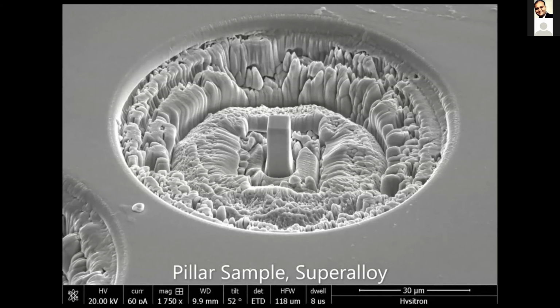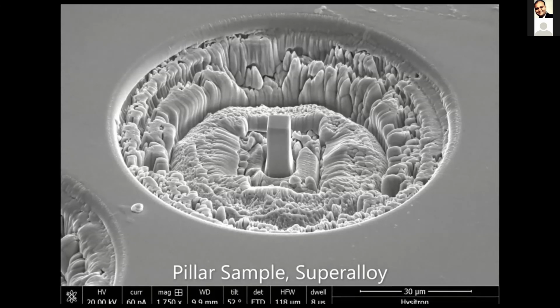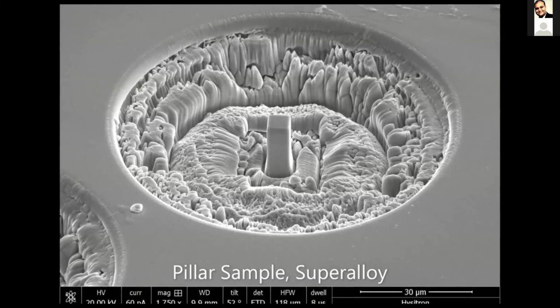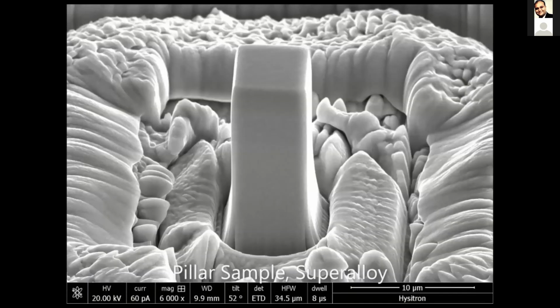So here we're using a square cross section, and each side is tilted in 2 degrees to remove the natural taper from the FIB process itself due to redeposition of material as you're cutting it away. These pillars are 6 microns across and about 16 microns tall. This is a good aspect ratio to use to avoid buckling if the pillar is too tall, or barreling if the pillar is too short. You also want to choose a tip that's a little bit bigger than the pillar to allow you to make good contact without blocking your line of sight.